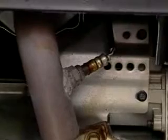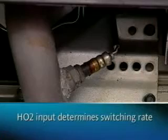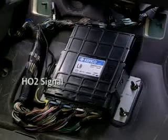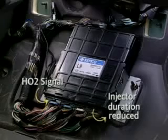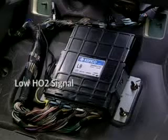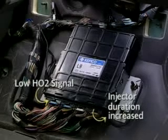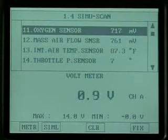The pulse duration of the fuel injectors is changed by the PCM in response to the switching signal from the heated oxygen sensor or sensors. When a high voltage signal from the HO2 sensor is received, indicating a rich mixture, the PCM decreases the pulse duration of the injectors to cause a lean mixture. When a low voltage signal from the HO2 sensor is received by the PCM, indicating a lean mixture, the PCM increases the injector pulse duration to cause a rich mixture. For optimum catalytic converter operation, the mixture must switch from lean to rich at least 5 times every 10 seconds.